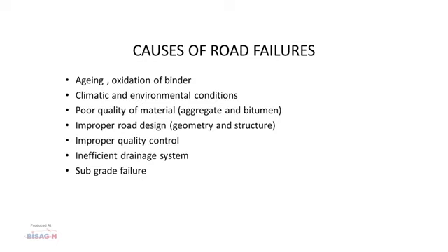The next is subgrade failure. Subgrade is basically the foundation of the road. If the subgrade fails, ultimately the road will fail. Hence, subgrade has to be compacted to its maximum density and it has to be maintained also.